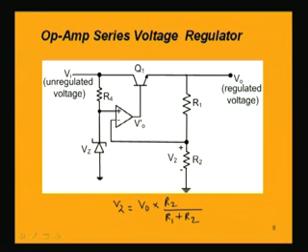Now this op amp is like a comparator, it is a comparator circuit, it is comparing the two voltages which are present at the non-inverting and inverting terminals. So what will be the output voltage from this op amp? Let us name it as V0 dash. That will be dependent upon the differential input present between the two terminals.